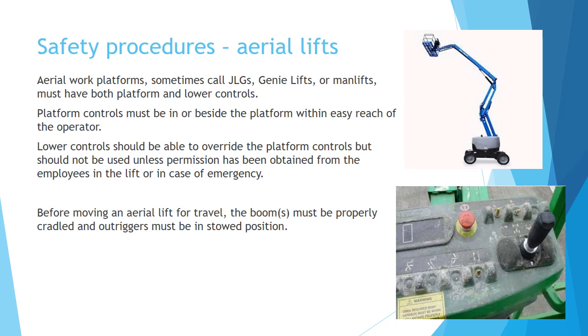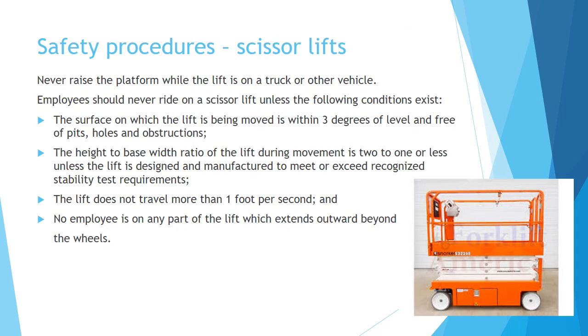Before moving an aerial lift for travel, the boom or booms must be properly cradled and outriggers must be in a stowed position. For scissor lifts, never raise the platform while the lift is on a truck or other vehicle. Employees should never ride on a scissor lift unless the following conditions exist.